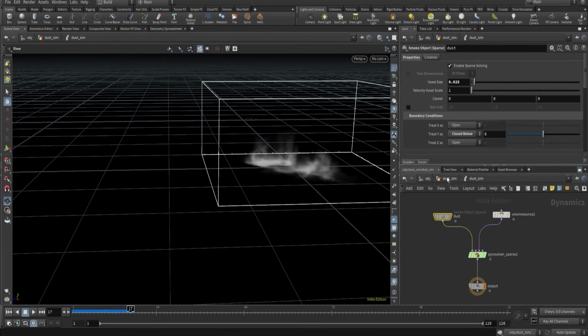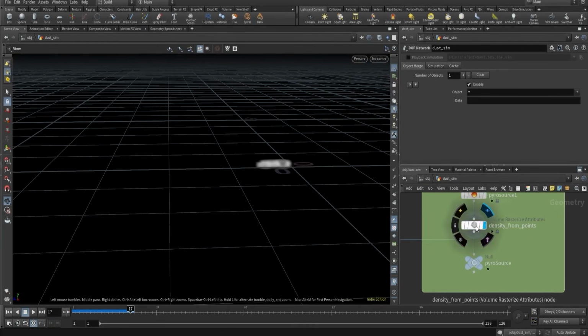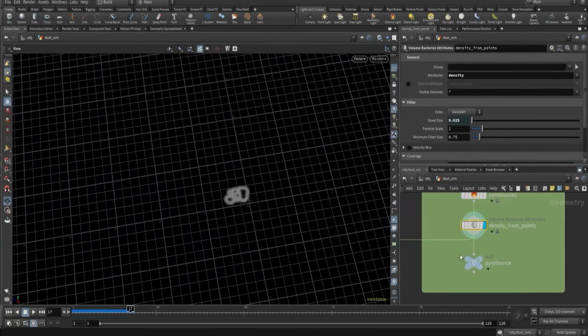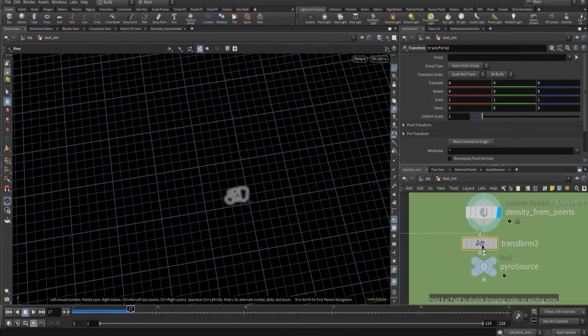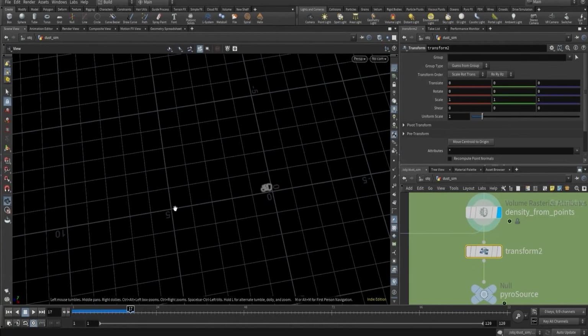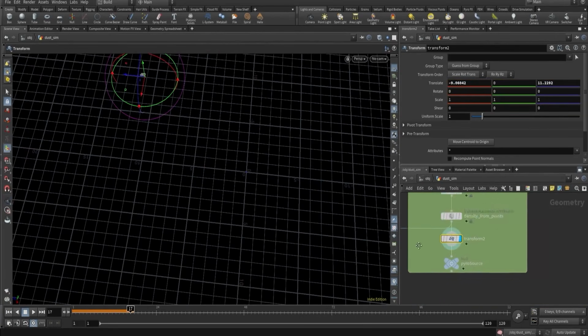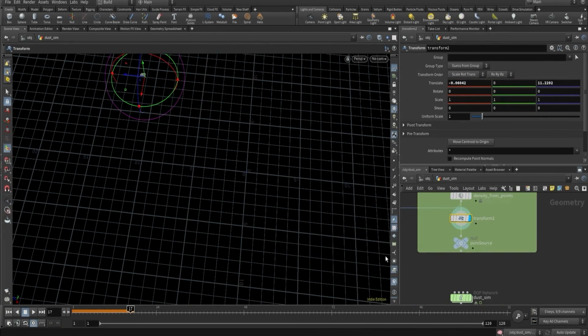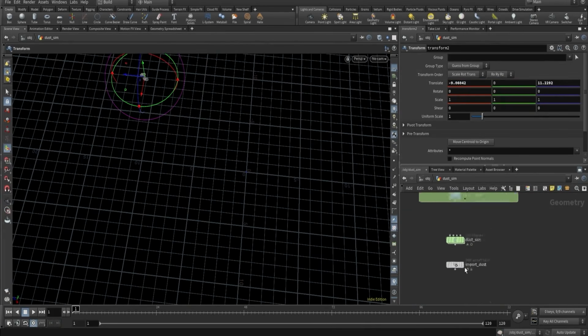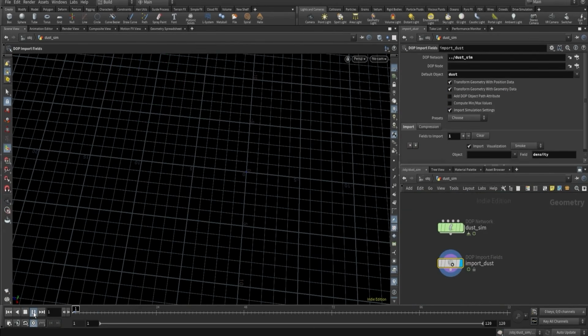And one more tip I wanted to give you. As you can see, this is really close to the grid, right? If it's not close to the grid, so it is somewhere here in the axis, will it still simulate? The answer is no. It's not simulating. So why?